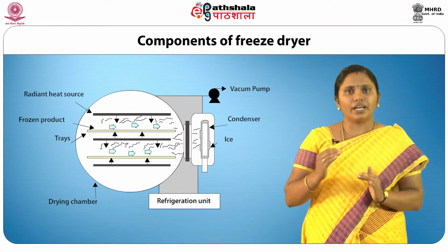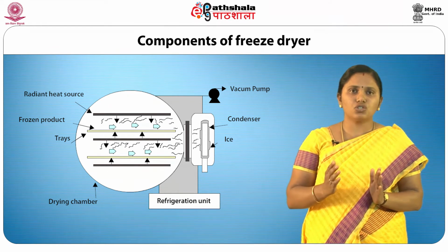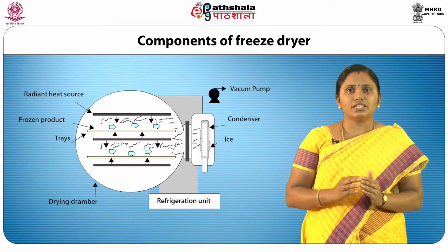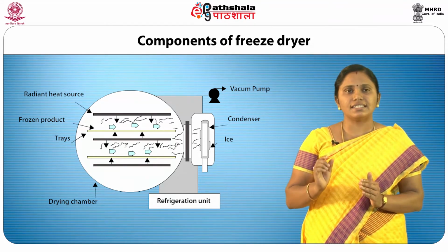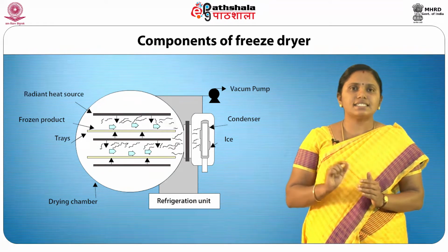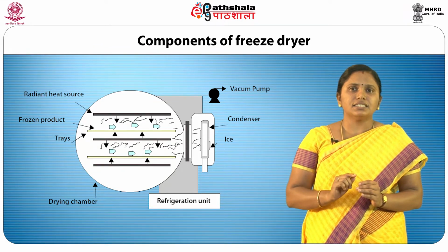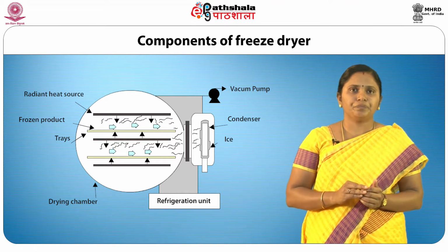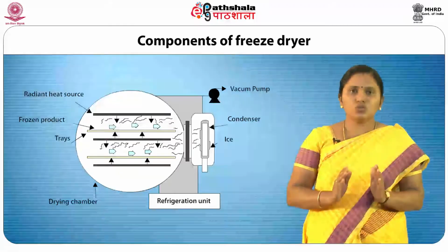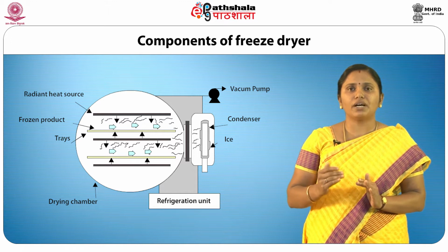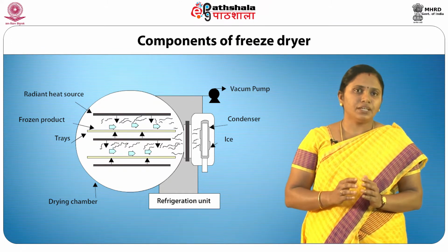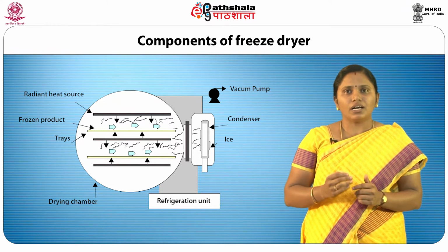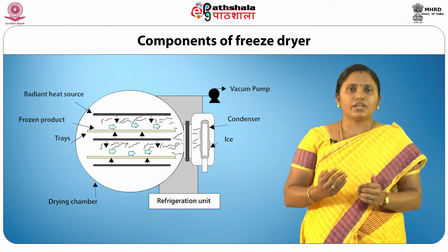Conduction and radiation types of dryers are used for commercial purposes. For most commercial freeze dryers, minus 65 degrees Celsius is used as the condenser temperature. The condenser collects the water vapor that is released by the product. Coffee is the most common drink produced by freeze drying technology. Liquid foods, small fruits and vegetables, and green pepper are highly suitable for the freeze drying process.